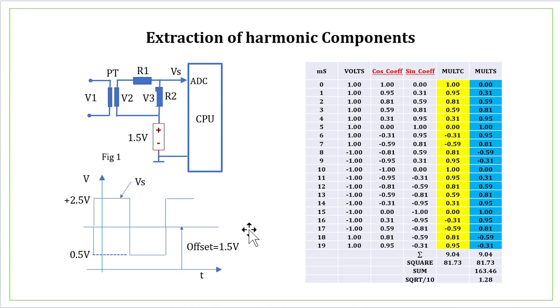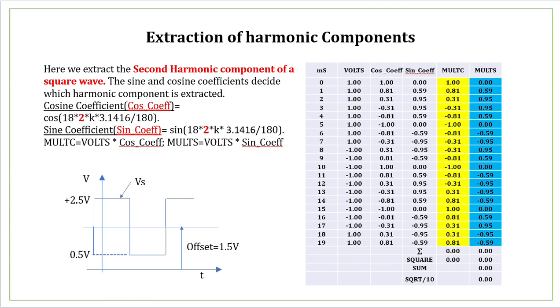So in this slide, oh, I have repeated the slide. Let us take this slide. Now we are taking second harmonic of the square wave. And we know that if there is a repetitive waveform, symmetrical repetitive waveform, its even harmonics are all 0. It will only have odd harmonics, first, third, fifth, seventh, ninth, and so on. So this will not have second harmonic, but let us verify.